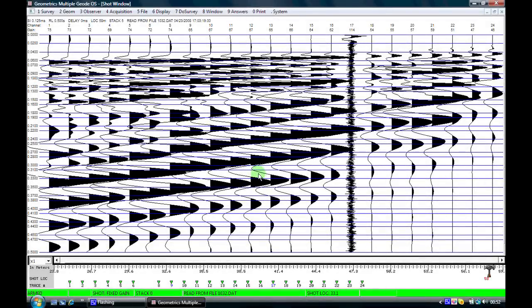This slide is a typical seismic refraction record, which I will now explain what we're seeing on the screen. Across the top we get our geophone numbers from 1 across here to number 24. The second row, which we'll see later as we make some adjustments, is our trace scaling factor, which is applied to each of the geophone channels.